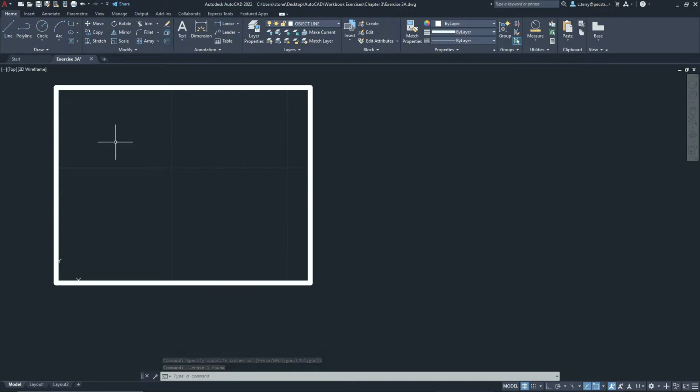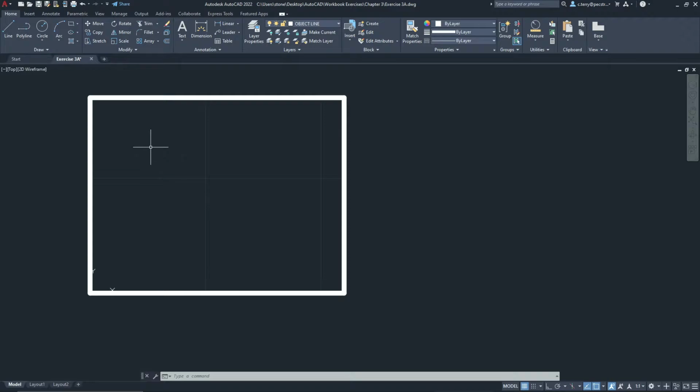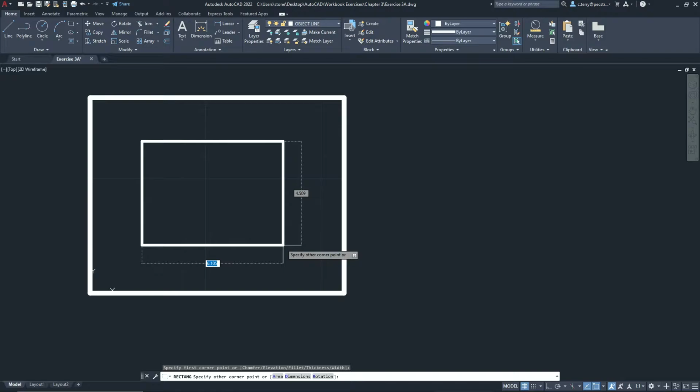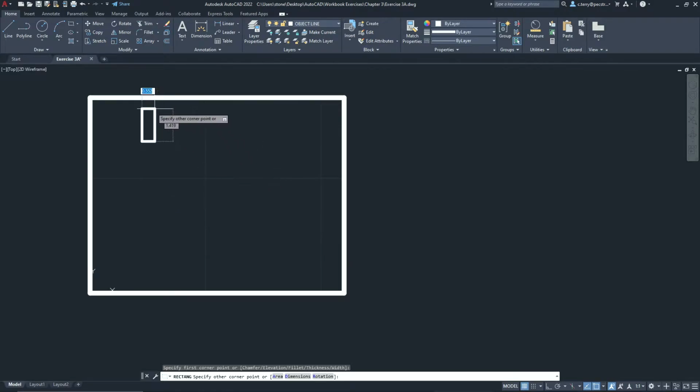You have different options. So the next command we're going to cover, if you go to sheet 3-4, is the rectangle command, and it's basically just a closed rectangular shape. You can use it for a square. It's one object, not 4 individual lines, which means, if I go here and I click rectangle, and I click my first point here, and then it wants the next point here. And you can go any way with this.